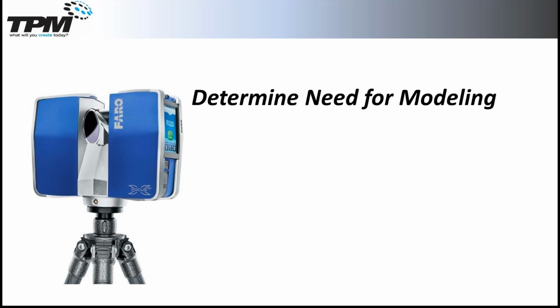Once we have our point clouds registered and ready to go into our CAD software or Revit and then a PDMS suite, whatever we need to use, we have to ask ourselves a question: what do we need to model? The point cloud by itself is incredibly useful. We can measure from any point to point. We have, again, the panoramic photographic images. That in itself is fantastic and changes the way we work and makes our job easier. But it's not a 3D model in the sense of working with solids or Revit families or specific piping information. And so, depending on the type of job, you have to determine what you need for modeling.